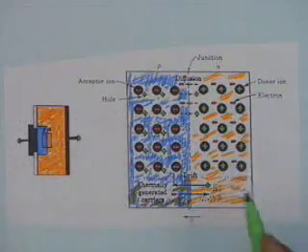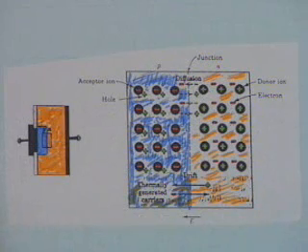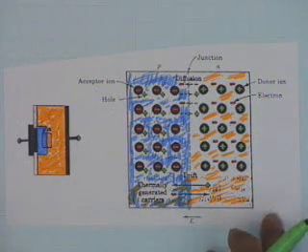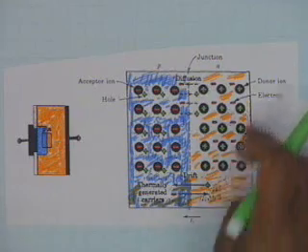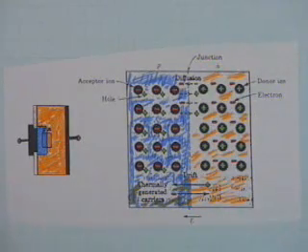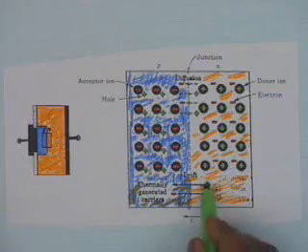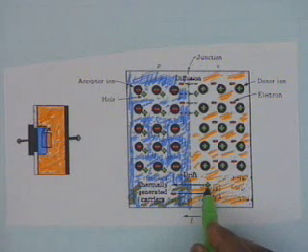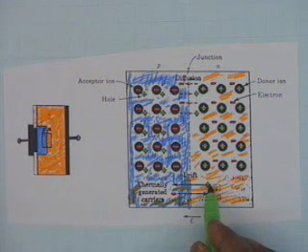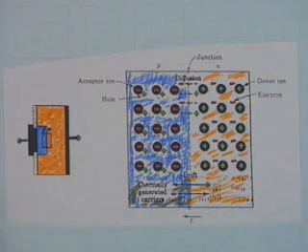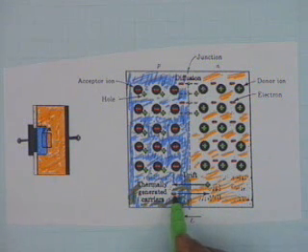Obviously, drift shall cause holes to move from right to left and electrons to move from left to right. Now, holes in the right region, that is N-type region, can occur only due to thermal generation. So it is these thermally generated holes, these green plus signs, they move under the action of drift or electric field from right to left, and these electrons, which are also thermally generated, they move from left to right.